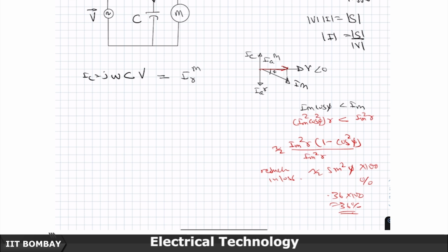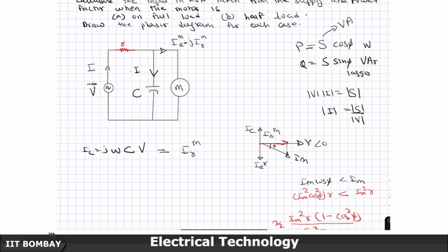So, therefore, the utilities, the distribution companies, basically enforce that your power factor should be close to 1 per unit, and if it moves away from a small band of say 0.95 to 1, then they will start putting a penalty for poor power factor, because you are now responsible for creating a societal loss which is happening in these distribution wires, transmission wires, all the way up, it is propagating.